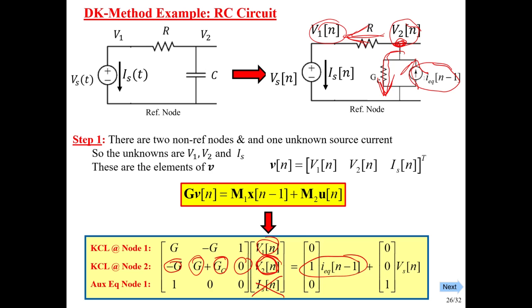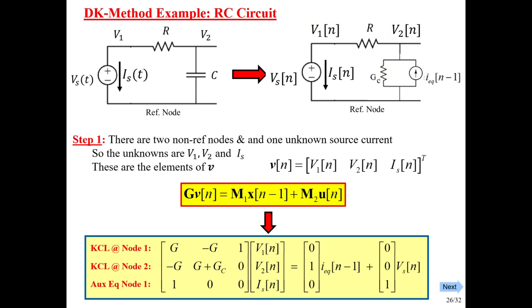And then what do we have left? Let's just look. I know that I have to have some combination of these things to give me one more equation. So what is it? Well, it's V1 is equal to Vs. So that's a common structure here: since I know a voltage there, that's known, I can link it to an unknown node voltage.